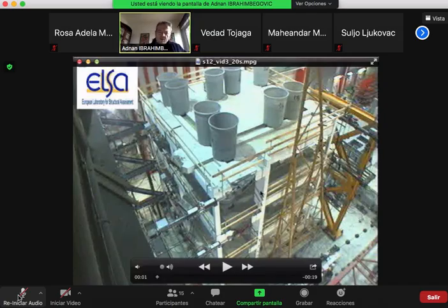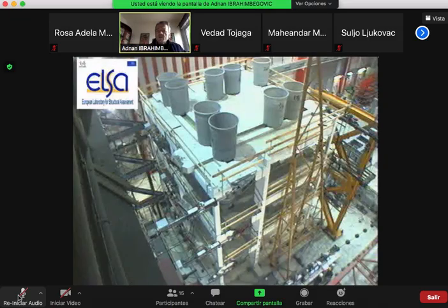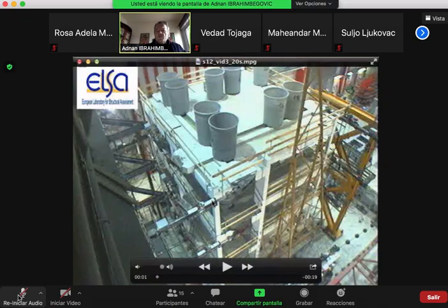Typically a two-story building with nice balconies and maybe not symmetric, because it is supposed to look beautiful. Then you fix the structure, you bring a real-life structure, meaning you construct it the way it is constructed in Greece, and instead of running an earthquake, because it now becomes too heavy and you cannot put it on any available shaking table, you start pushing the floors of the structure the way an earthquake is supposed to do.